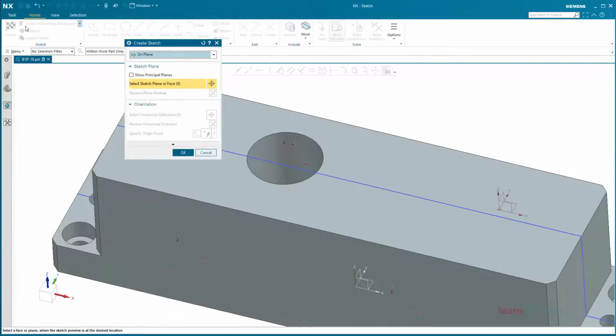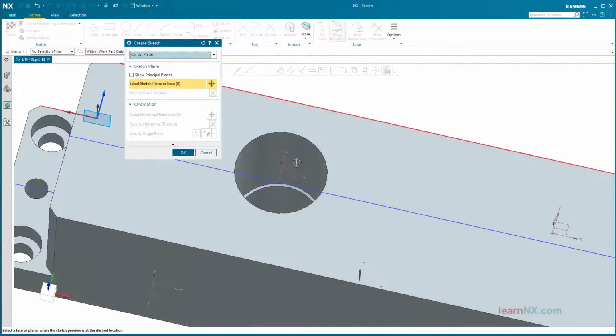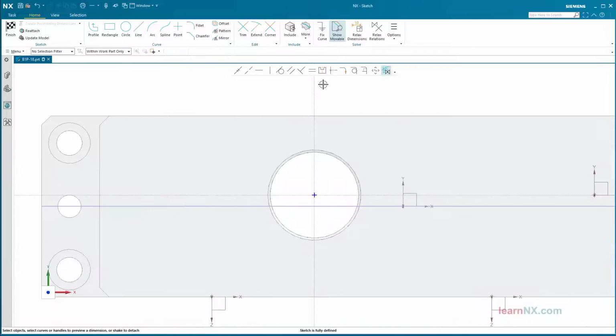Place the pocket sketch on the XY plane of position 1 to fix the sketch origin to the reference coordinate system. Create a rectangle using the from center rectangle method. Select the sketch origin as the center.